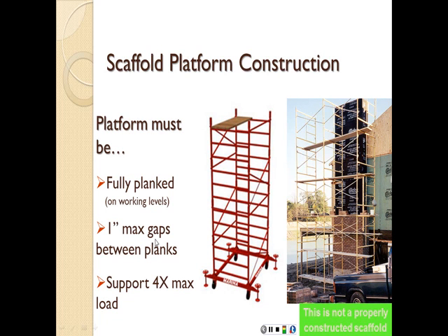1 inch maximum gap between the planks. If you're going to place them next to each other, there's going to be only 1 inch maximum gap, again to prevent the hazard of tripping or falling debris either. And it has to support 4 times the maximum load. That's per the specifications for a proper scaffold.